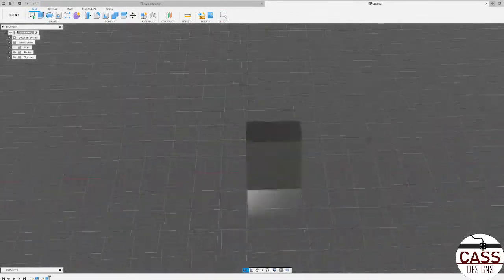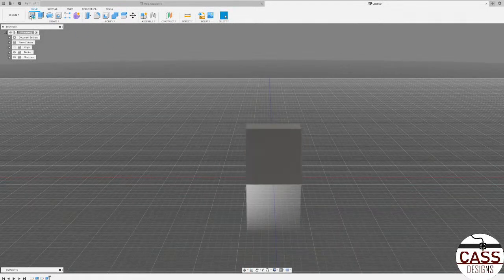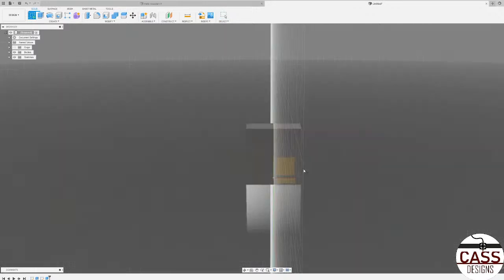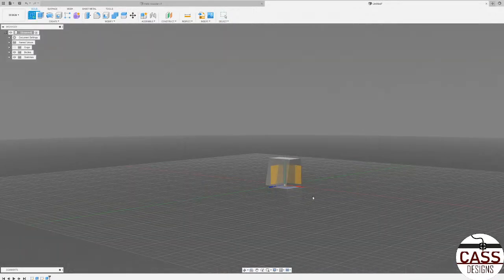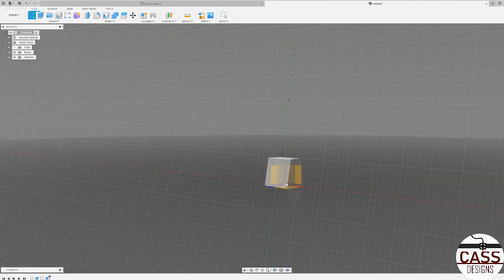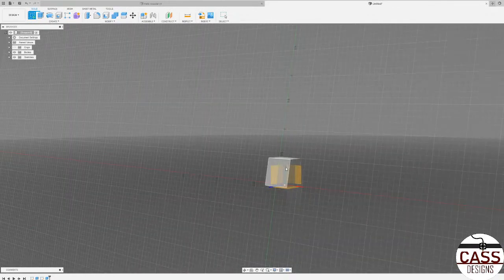So now we have that, and this isn't really going to look that great of a keycap, unfortunately, but just to kind of show the general design process. Then you click create sketch again, and this time I'm going to click on the XY plane, because I got rid of the flat planes on the sides of the keycaps when I made that cut, and I don't want to cut at an angled down surface, as you can see this creates when I highlight over it.